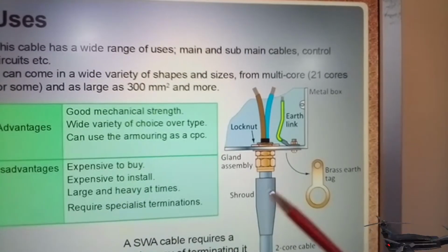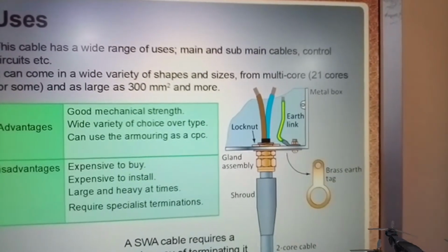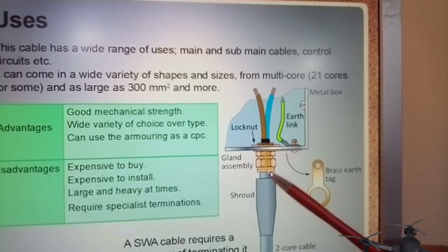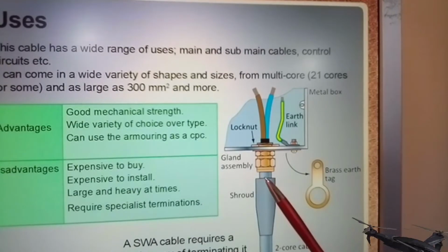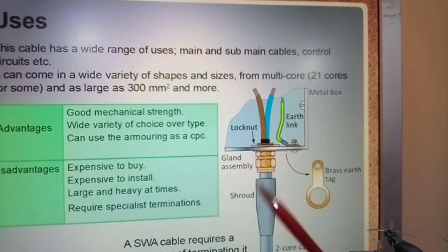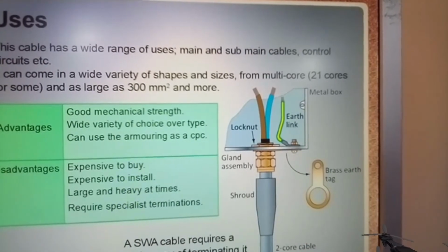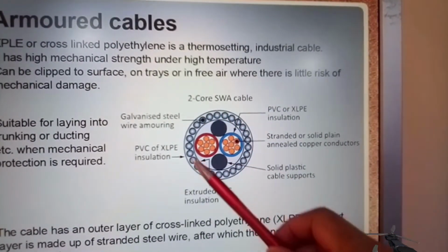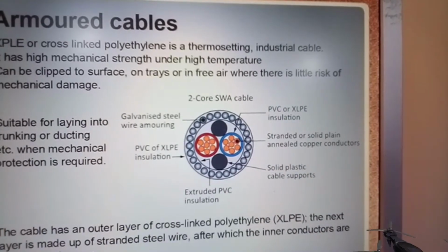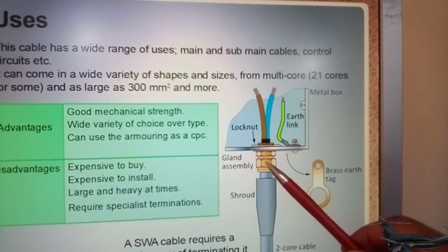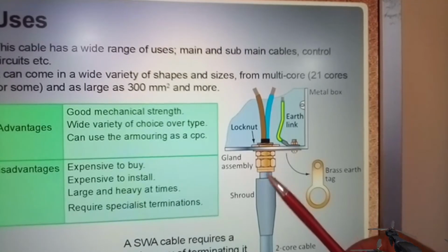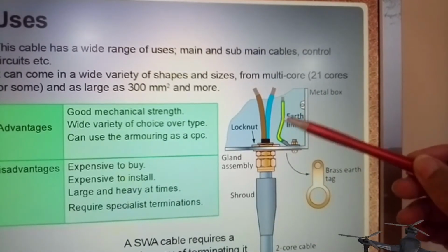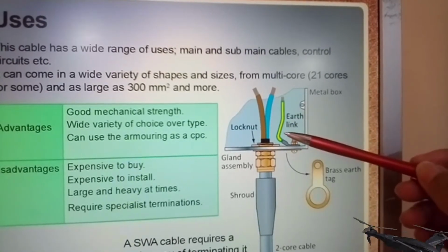Here you'll see that your flange bonds your cable here. Now, for whatever reason, let me just go back a little bit. These galvanized steel wiring outer armoring here will form your earth bonding as well. But you'll see that it is always advisable to have an independent earthing as well, okay.